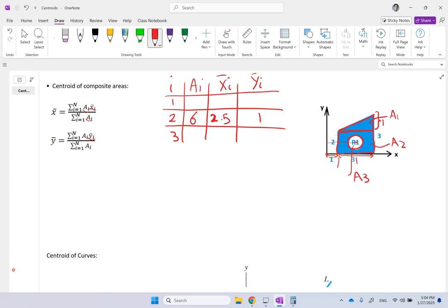Remember here, the right side is entirely 3, so for a triangle, that is just 1. For the triangle, this is your triangle. And in general, if your triangle has this total width of W and the total height of H, the centroid is here. And where is that? Well, it's 1/3 of W from the base, so it's this much. That is W over 3. And also 1/3 of the height from the other base, which is this one, so that is H over 3.